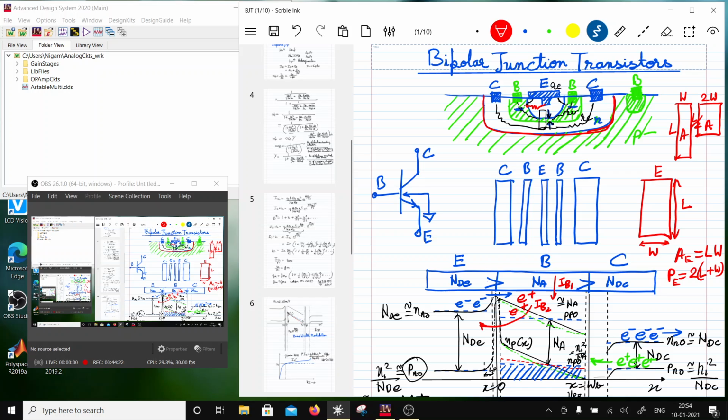The transistor on the right, which is this one, has half the power capability of the transistor on the left one. Why? Because the periphery is now halved, because the major portion of the periphery is the length, and if you have half the length, that means you have half the periphery.